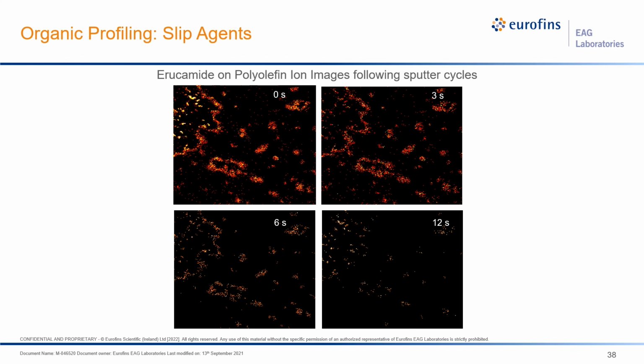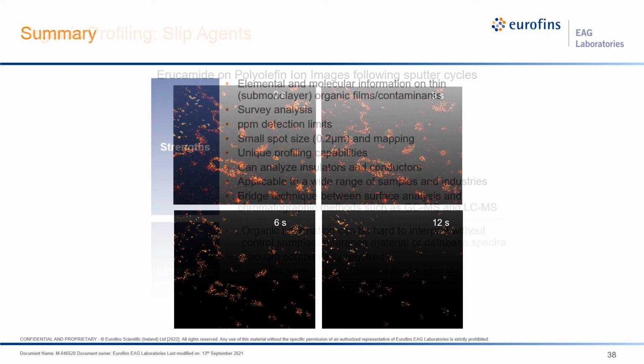So you can see we're successfully removing the material, but not really destroying it because we still get some diagnostic information. Okay, that's the end of the examples, and I'd like to hope that we've given you a flavor for the type of information that TOF-SIMS can obtain during an analysis that can incorporate a mixture of mass spectrometry, ion imaging or mapping, and also depth profiling into the material. We don't always need all three of these, but for complex examples, it may be a case where we would take a large data set like that.